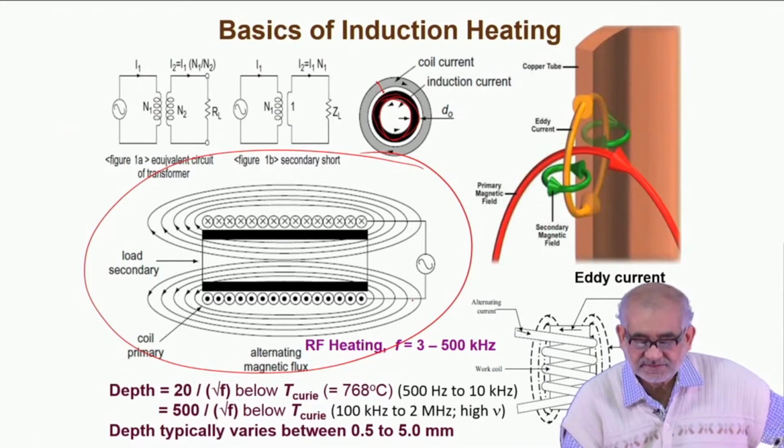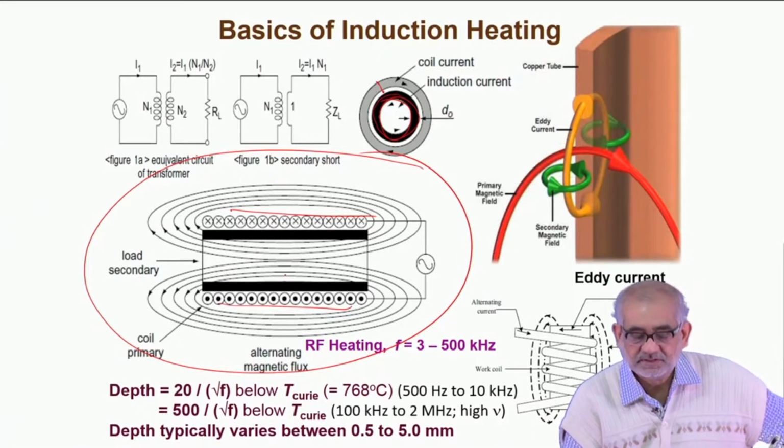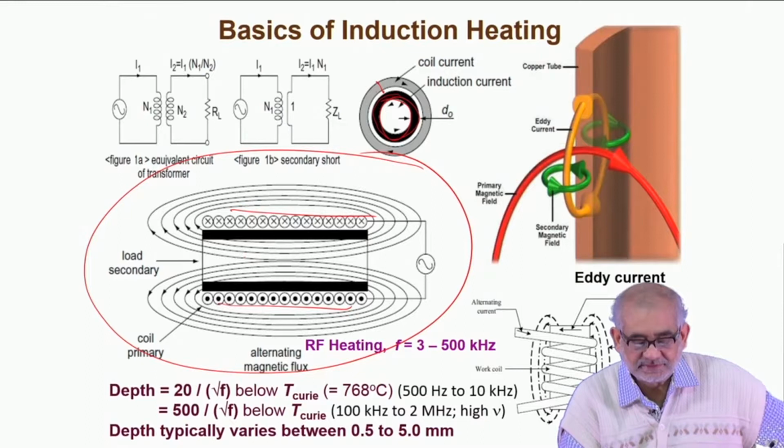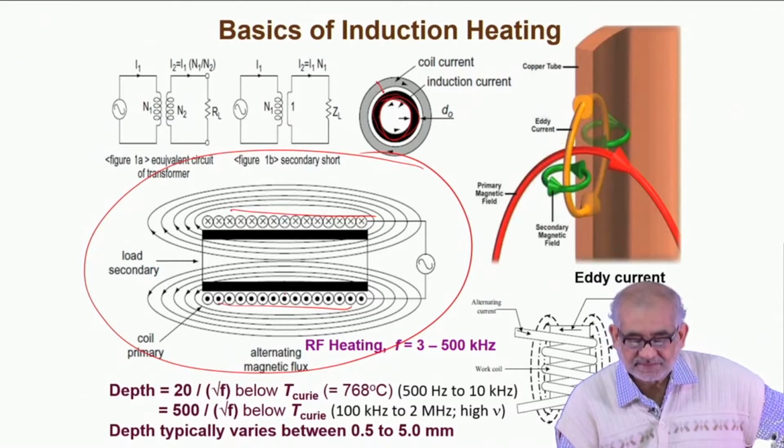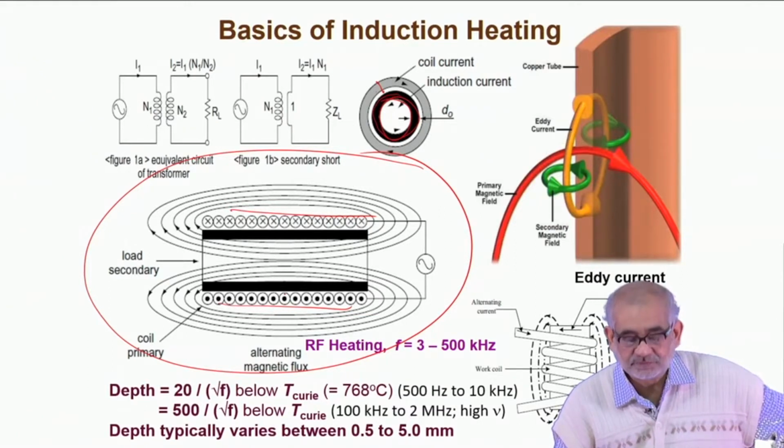These are the fluxes created from the induction coils, and the coils are perpendicular to the stock, and this is how the flux is generated, by the left hand thumb rule. Then these fluxes intersect the surface, and if the material is magnetic, we get even better or faster heating, and that's very true for ferromagnetic materials like steel.